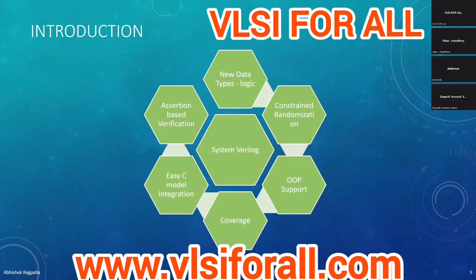So these are the major strengths of SystemVerilog. It has new data types, for example, logic. Logic is a very strong data type, and I will discuss more about it. Logic has really made SystemVerilog very strong, and now we don't really have to care much about reg or net, all that we used to do in Verilog. And then there's constraint randomization.